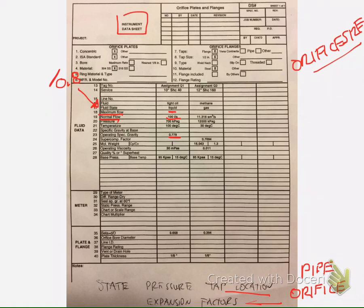We've got 100 liters per second divided by 1,000 liters in a meter cubed, multiplied by 3,600 seconds in an hour, and also need to multiply by our density of 778 kilograms per meter cubed, and then I need to divide by 0.8, so I get a value of 350,100 kilograms per hour.